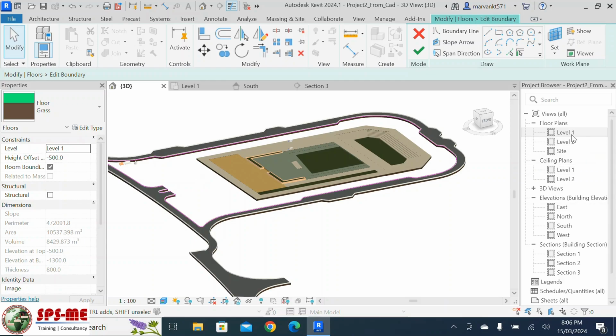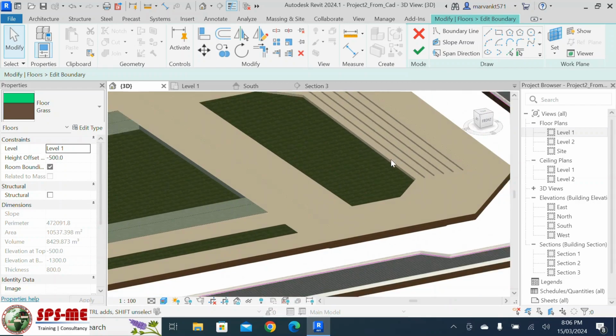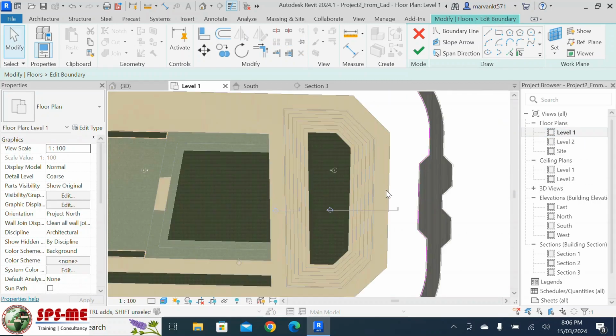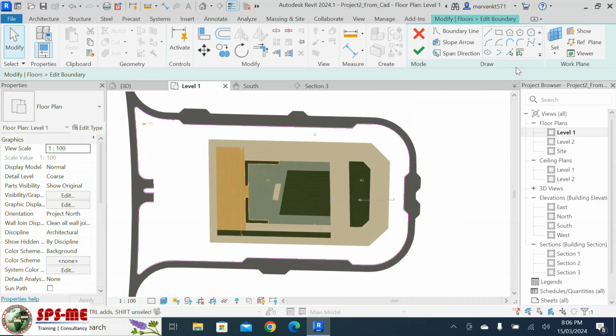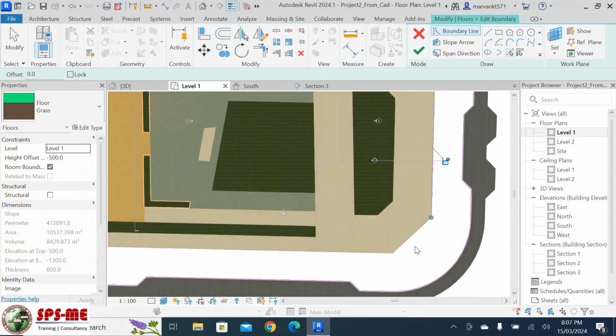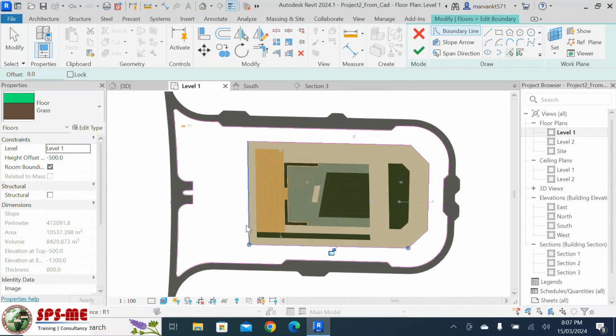So you can just go to the slab which I placed over here, that is together, I mean completely a single slab. But now I'm going to cut this area because I have already constructed that over there. See here now. So you have to go to the level 1, then you select pick lines, then you choose the edge of those slabs we have already created.